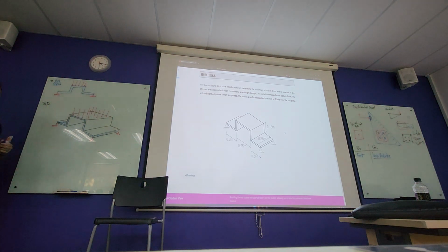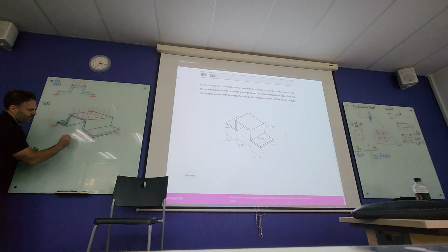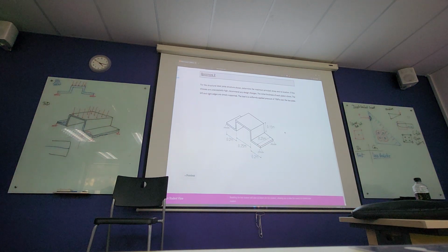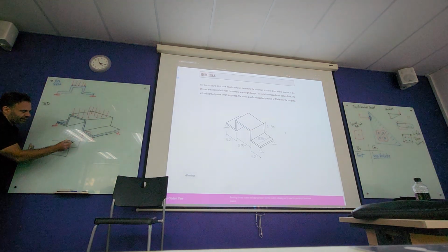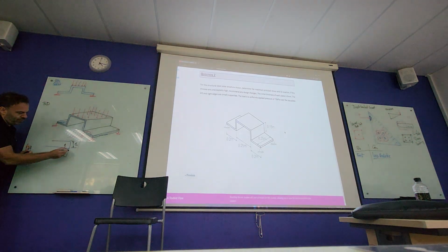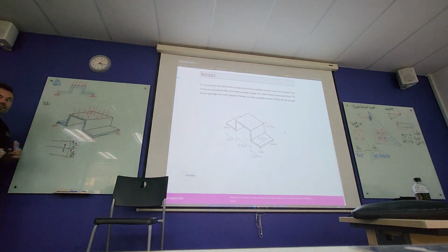And everything else. If we take this bit out and zoom in there, you will have a thickness like that, and you've got your mid-surface. Now, a surface doesn't have thickness. So mathematically, we would assign half of the thickness to that side, and half of the thickness to the other side.